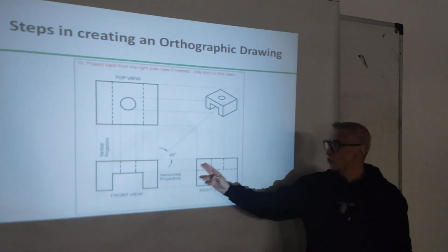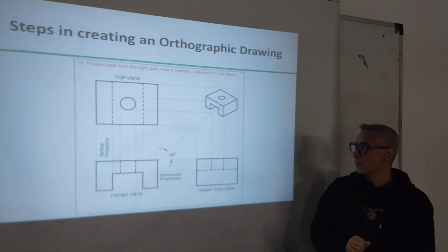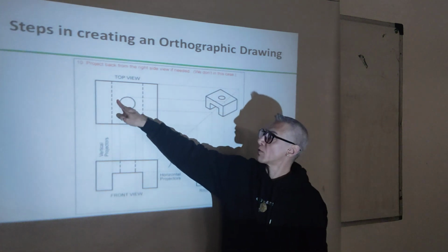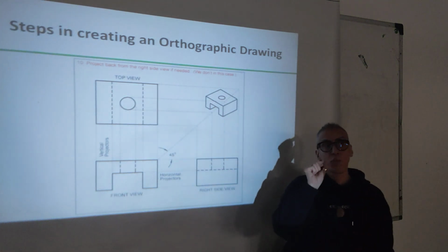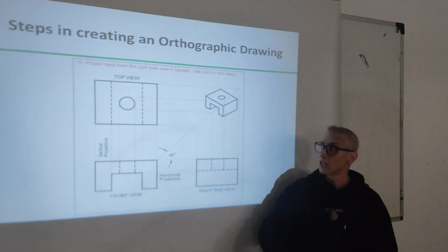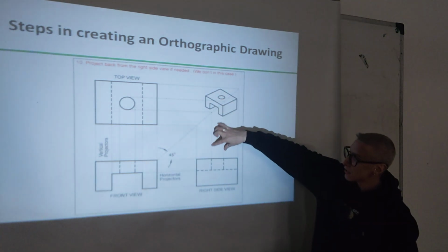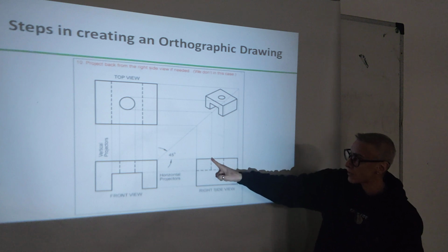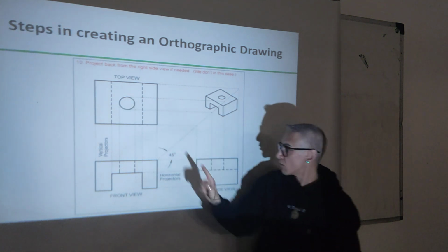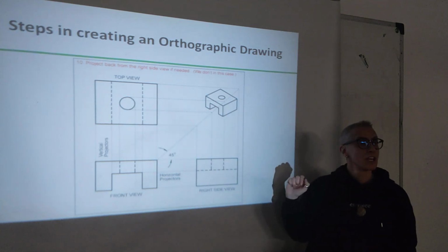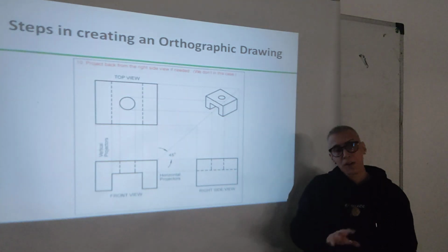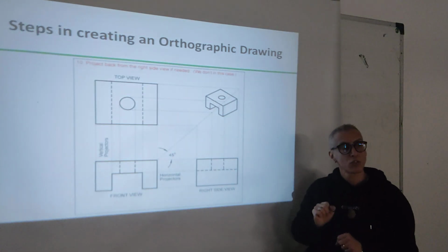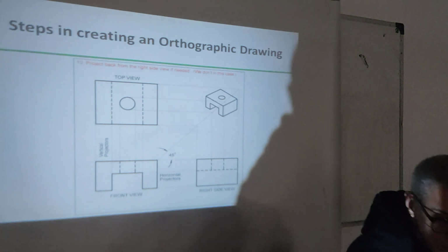And of course, then you draw the details of the right side view. As you can see, this one from the top, we see it as an object line. It is an opening. But when you take it here, go down, this becomes just a line. And what is inside, we see it as hidden. Whenever there is a hidden object, you also need to show its location. Okay?